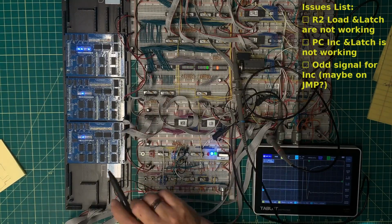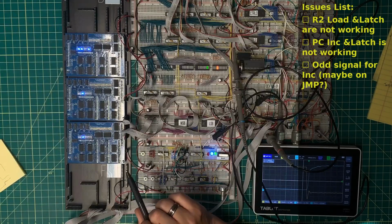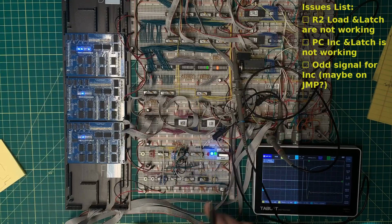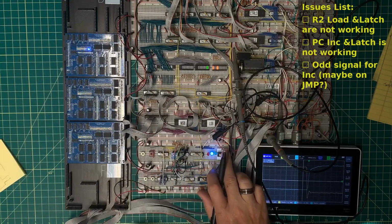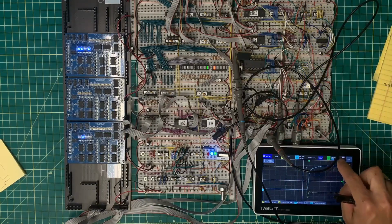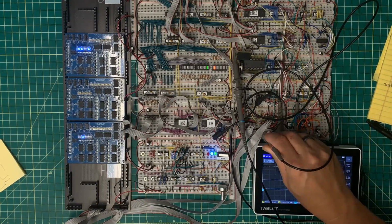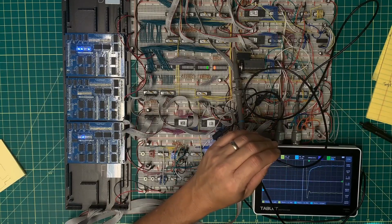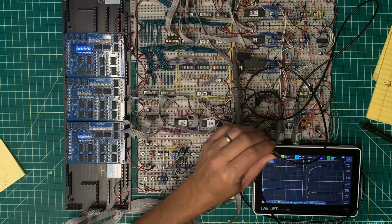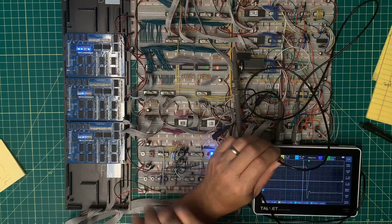Okay, there is definitely something going on here. The first instruction fetch is correct, but the increment and latch is not happening, which I thought was a good signal, the load, increment and decrement. And I'm reading those in the correct sequence, so increment is going to be 2, binary 1, 0 on that signal. So reset.